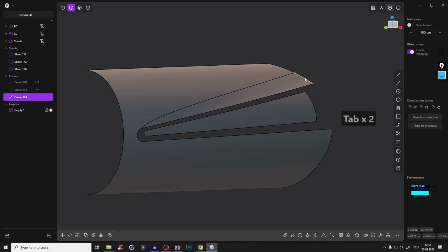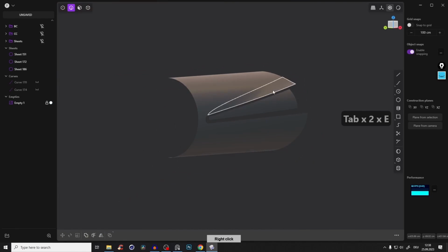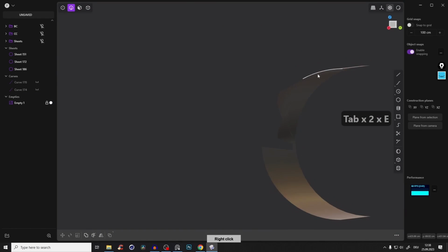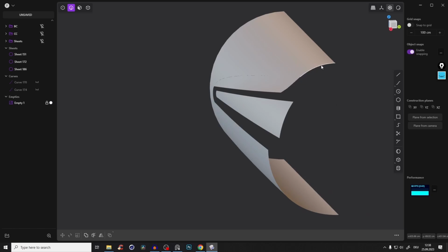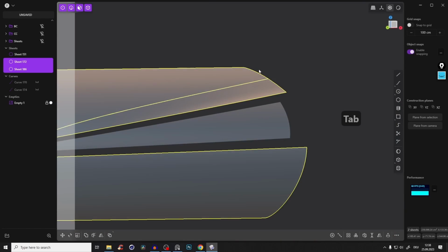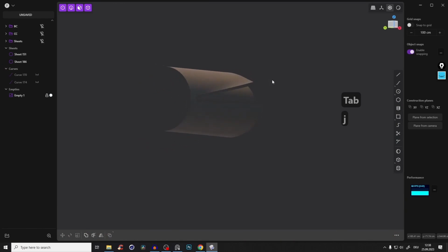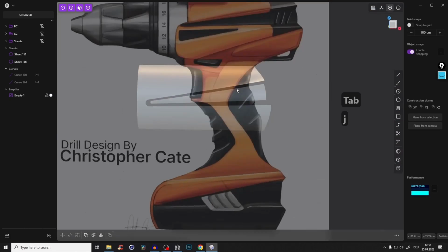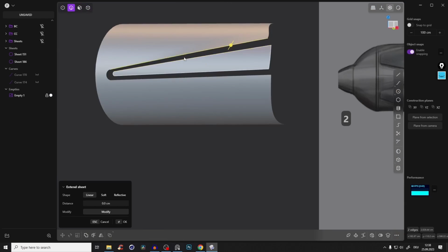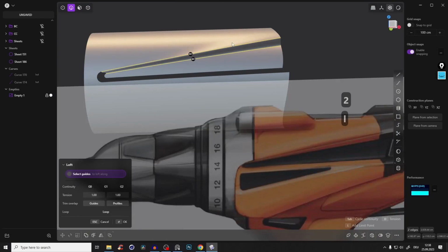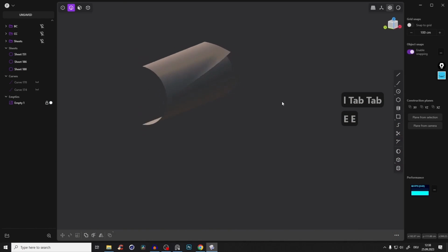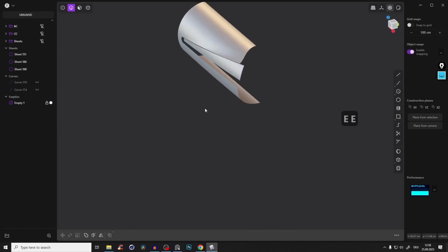So we can delete the surface, delete this curve, and you see that looks fine. Here you see it's going a little bit, and we have this really cool shape. And if we join those two surfaces, you see we have a very beautiful smooth transition. And now we can select those two edges and loft them with G0 and press OK. And we have basically our first detail.